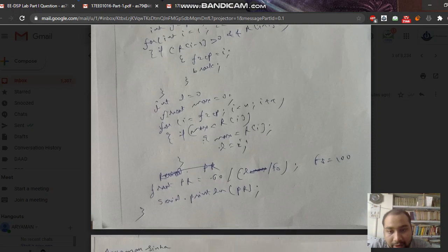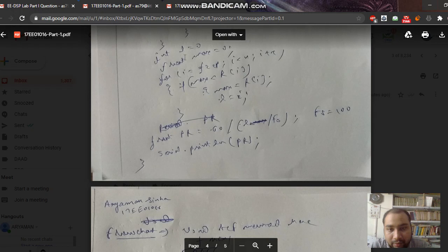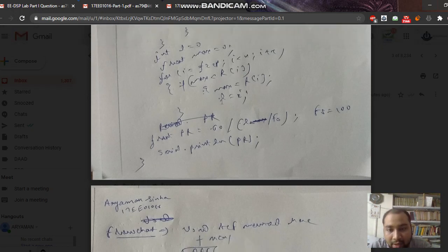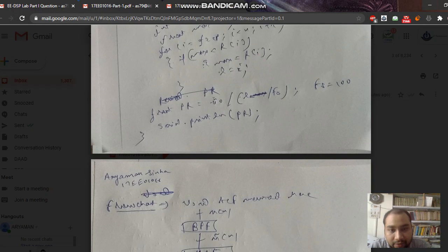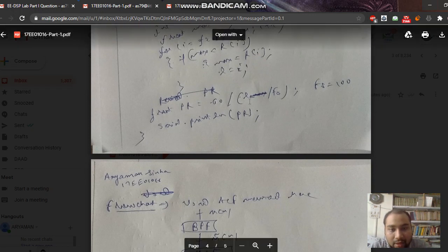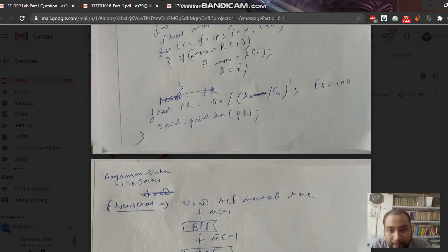So wait for a minute. Then we use the autocorrelation function from the zero crossing point onward and find the second highest peak, which is L here, and the index is L here. For calculating the pulse rate, as we've discussed, it is 60 divided by the pulse period, which is L divided by Fs.